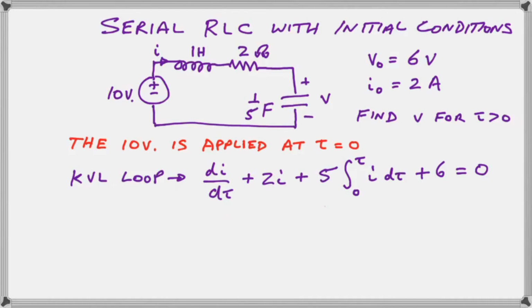So we have V equals IR, and i is shown, and the R is 2, as shown in the diagram. So that also is a voltage term. Then we have this term here, which represents the relationship between the current and voltage inside of the capacitor. We are basically integrating the current across time, and we have the capacitance here.